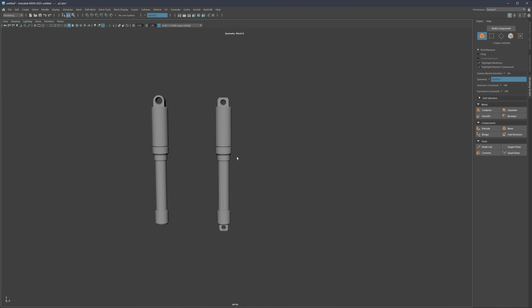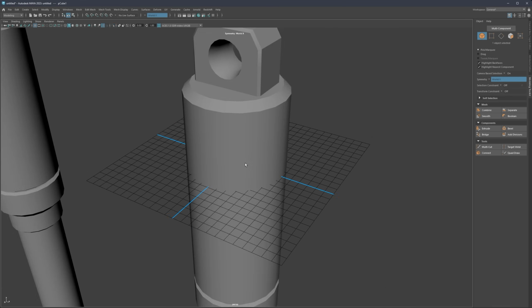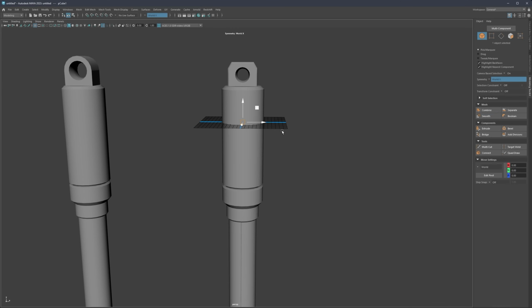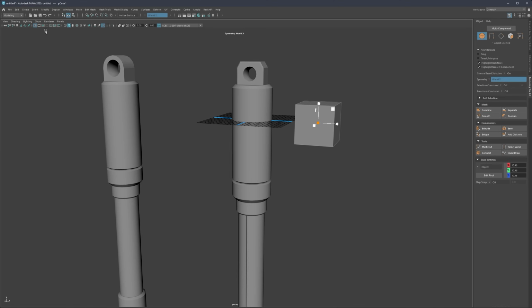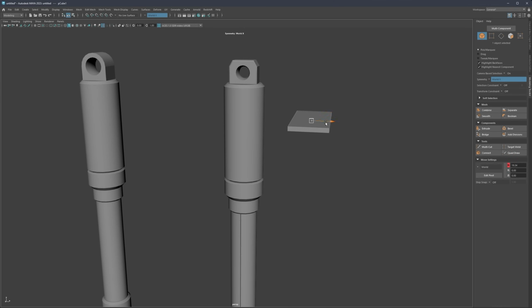Now the cube is not going to be visible, but if you want to see where the cube is, you can hit Control 1, and then if you enable the grid, you're going to see that the cube is actually snapping in the middle of the grid. And any kind of object that you create is always immediately selectable. That means that if you hit move, scale, or rotate, you can immediately push it to the side. And then let's say scale it. And let's just remove the grid, and I'm going to scale it down and push it to the side.